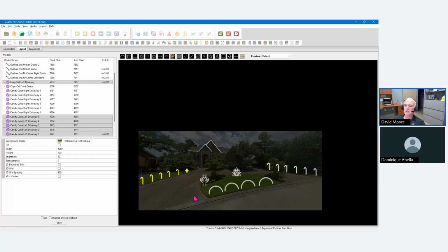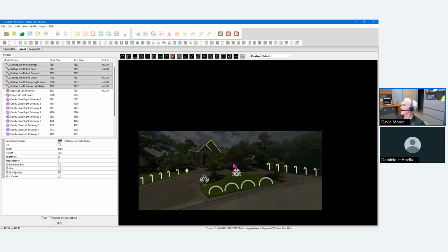During Christmas you just put these props up and take them down, they're not up year round, so it doesn't matter. But the receiver is not going to be able to do SD card playback or anything like that. It needs a controller to operate it, because the receiver gets all its data, hence the name, from the controller. So I would ask, are you going to be doing this house outline as a permanent, full year-round thing? If so, we're putting that controller up here and everything else is long range.